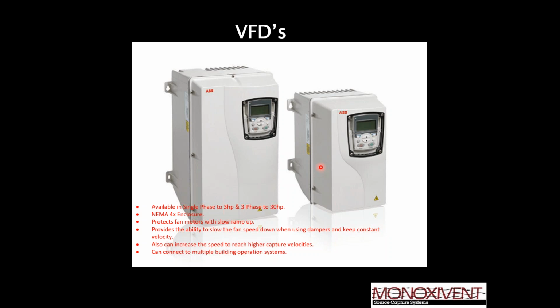So let's say it's 10 hose reels, 600 CFM per reel. It's not hard to find a VFD that would handle that. The problem is finding a fan that has a proper range that can go from 10 hose reels running at 4 inches of static pressure all the way down to 1 or 2 hose reels running and maintaining the static pressure and the velocity needed to remove that type of exhaust.